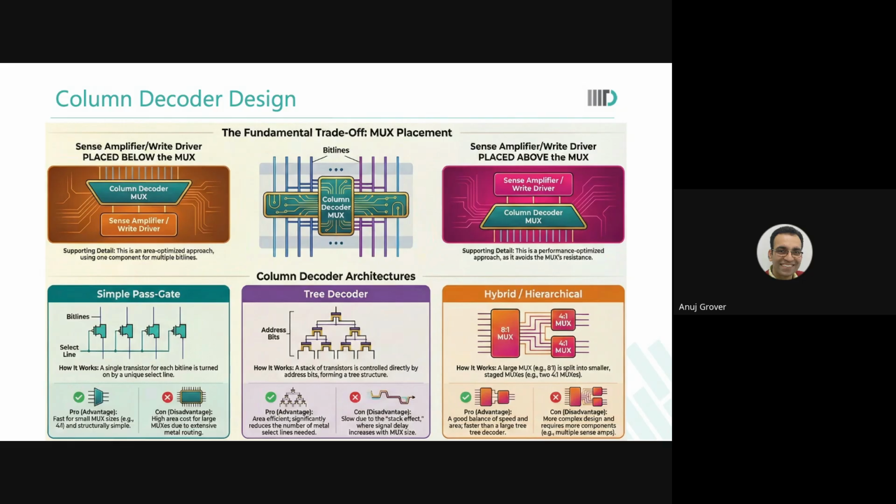We will talk about the sense amplifier just now, so we'll look at it then. What leads to sense amplifier offset? Whether you put an equalizer or not, does it even touch the sense amplifier? Can it therefore change its offset? How much you need to discharge the bit line, that may change. But does it change the sense amplifier offset? No.